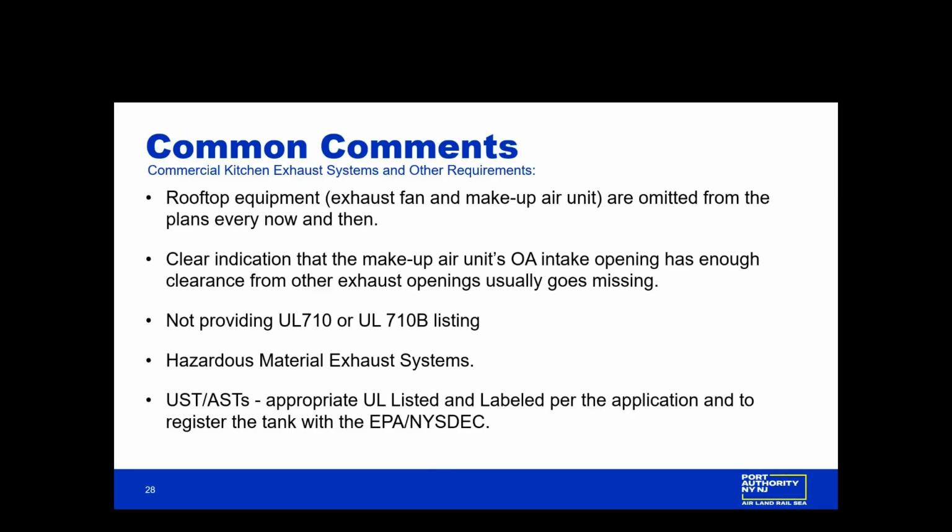We have USTs, ASTs, underground storage tanks, above ground storage tanks. Please provide the appropriate UL listing and label for the application, and please don't forget to register the tank with the EPA or the New York State Department of Environmental Conservation. Next slide.